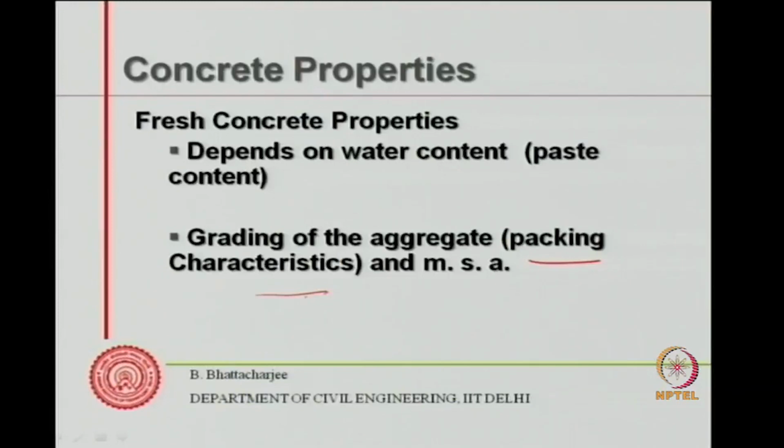That's a very important issue. So grading of aggregate, and we have also seen as I increase the maximum size of aggregate or number of sizes, my packing density improves or the void system in the aggregate improves. So good grading, higher MSA, they will always reduce down the void system in the aggregate, and therefore my paste content required for appropriate moldability or workability would be less. So it will make the concrete economic.